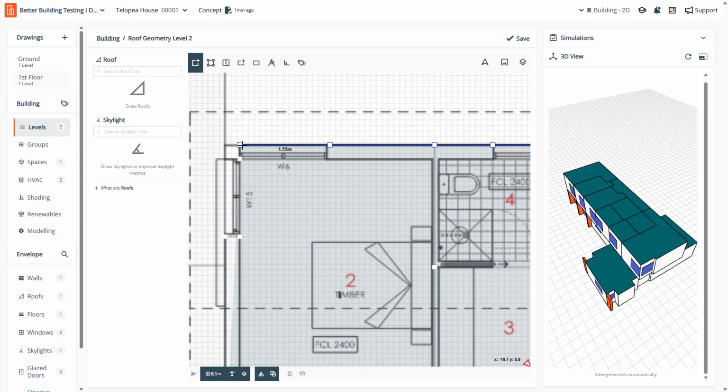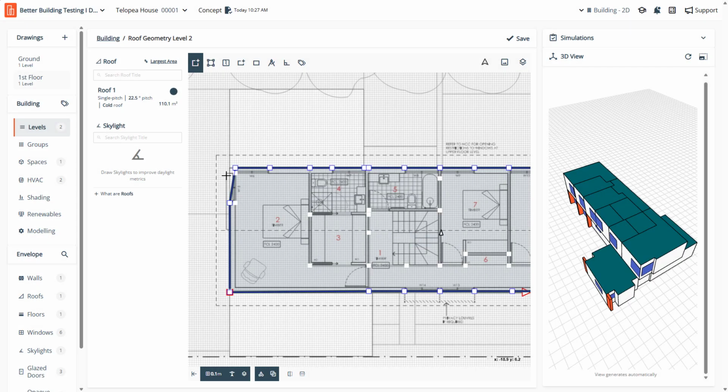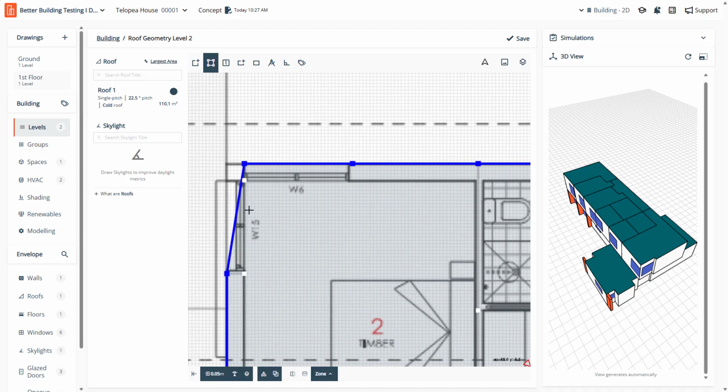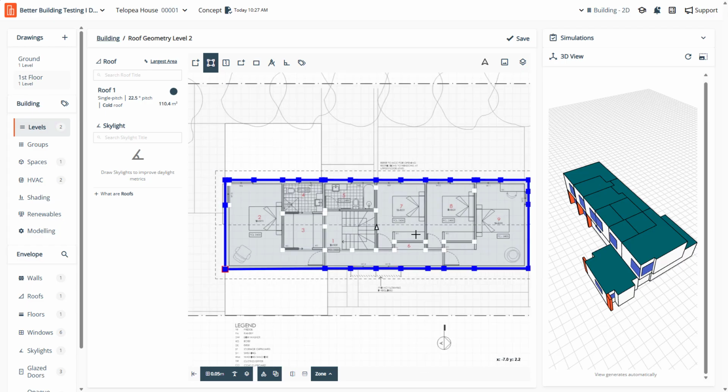So just going to bring that in there, and what I'm going to do, I can see that roof is probably wrapping around a bit. So let's call this roof 1, wrapping around a bit, as in overhanging there, not wrapping around. And then I'm just going to grab that there and square that off. So that's great. We've now got a surface that's going to represent a roof.